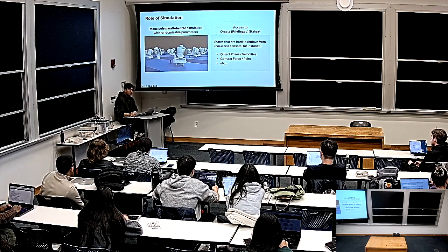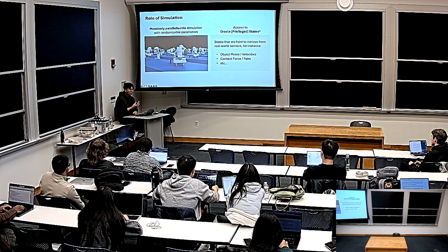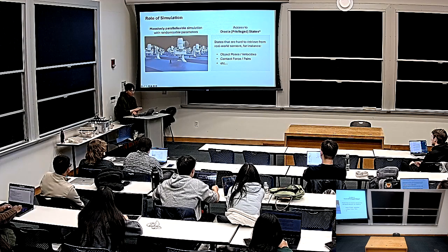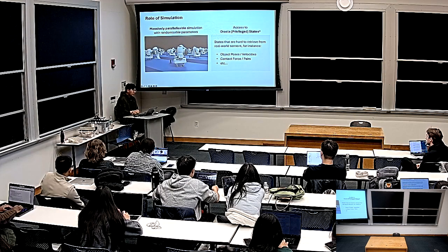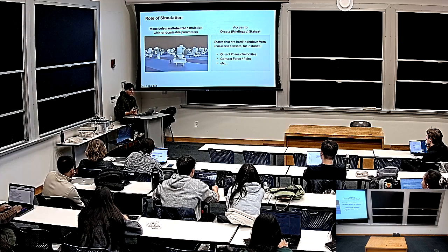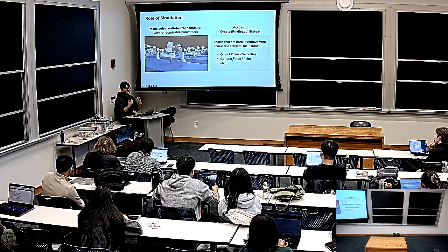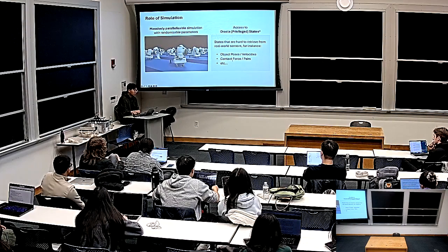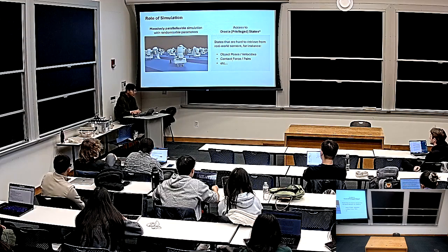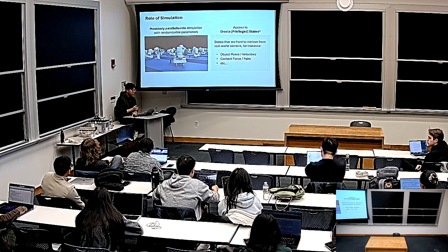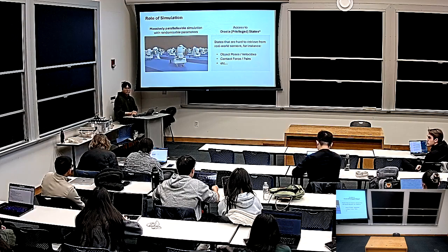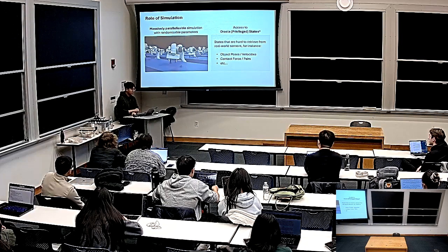But if the real robot has to infer the actual poses of these kinds of objects, it has to go through some pose estimators that are trained offline with different techniques, and those are known to be error prone. So the fact that simulation demos have access to those privileged states, including something like contact forces and contact pairs, makes those demos in simulation nicely paired with algorithms like reinforcement learning that can leverage the power of these kinds of features of simulation.